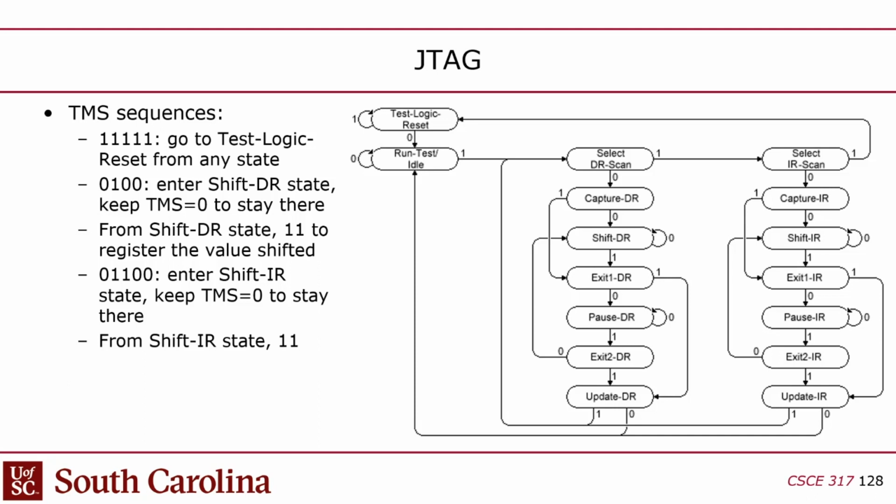The idea is that it's like a side channel. It's something that's very low cost, but it can give you access to a lot of stuff on a circuit board. It's slow, but it gives you really good coverage. You can basically read out the internal state of every chip on a circuit board just from this one JTAG chain that wraps around, and it's just 4 wires. So that's the idea: it was meant to be as cheap as possible, yet capable of debug.